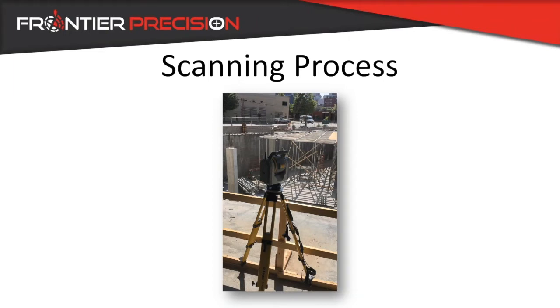With a traditional scanner, if you have things like vehicles or people moving through your scan, you tend to pick up a lot of things that you have to segment out, a lot of artifacts and ghosting. The SX10 is much less pronounced than the laser scans because you're doing an area multiple times. So oftentimes if an object comes through, you can still get the data that you need and not have as many artifacts or things that you need to segment out as you're looking through your scan data.